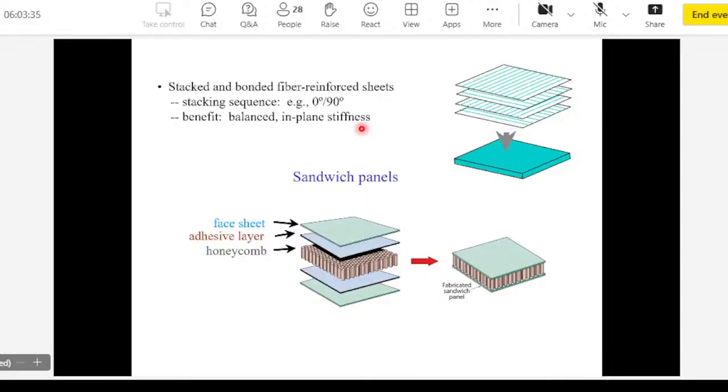The interesting thing about polymer composites is that you can actually lay the fiber or pre-pregs at different angles to get different properties. So the top here, for example, has 0-degree angle. 0-degree means that this lamina or this pre-preg is in the direction of the fiber. Now the next sheet would have 90 degrees, which means fibers are perpendicular to the previous orientation. Okay, 0, 90, 0, 90, this kind of an orientation, or many other kinds are possible.